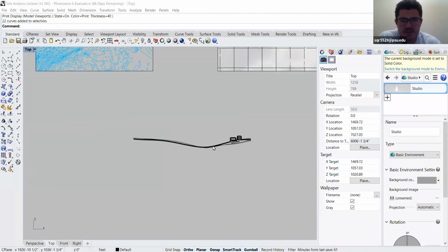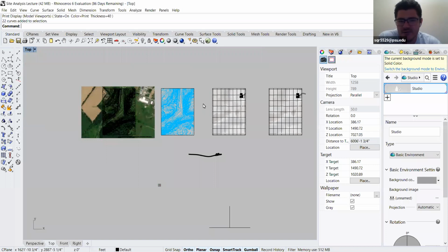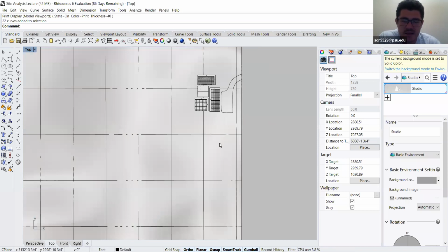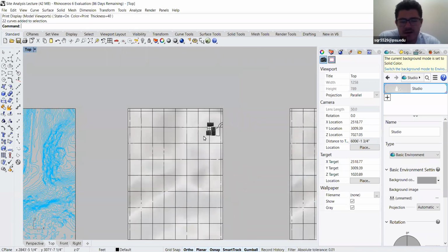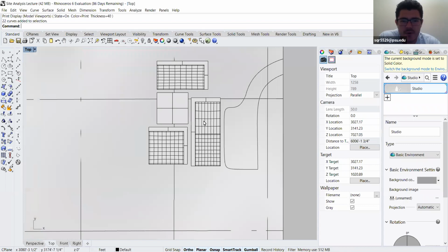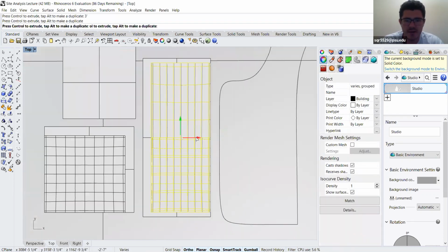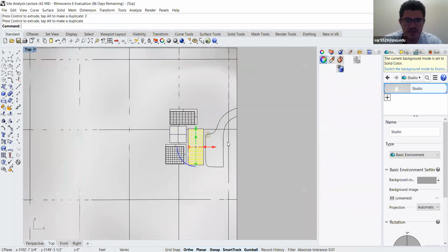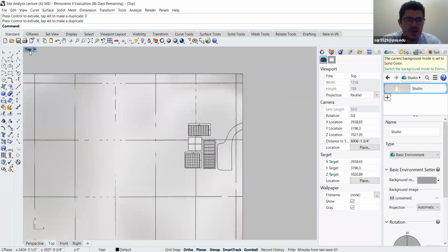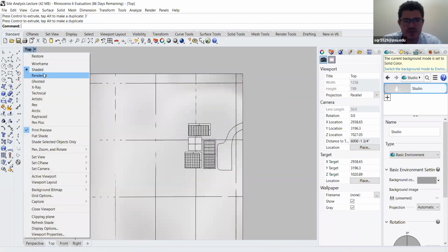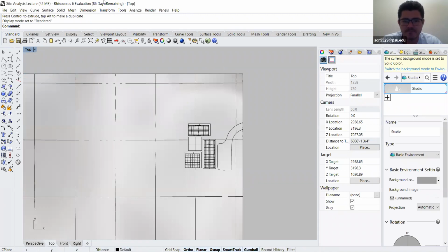So there's site sections. Another feature they wanted to let you know about is sun study. So having clustered buildings, how does that affect things, and how can you use Rhino to best use it? Let's go back to our site where we have our three buildings, and we want to see how the sun will affect their placement. Being in shaded view, it won't really show as much, so you go to rendered view.